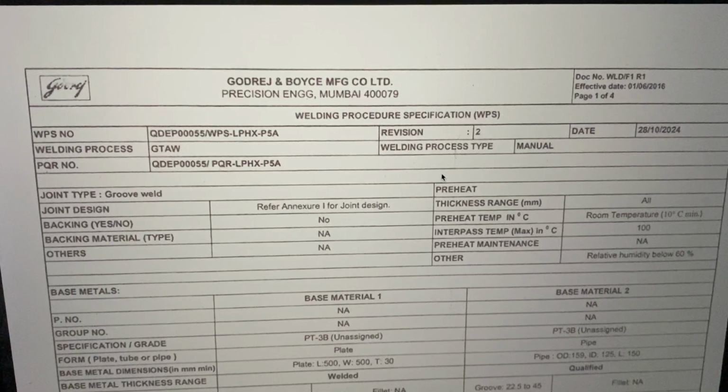And we should have a check somewhere between the weld point and the point where we are going to have a room temperature or a preheat temperature. So that temperature during welding or during a pause, when we are going to start the next run, is called the interpass temperature.